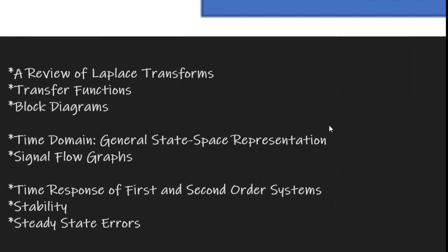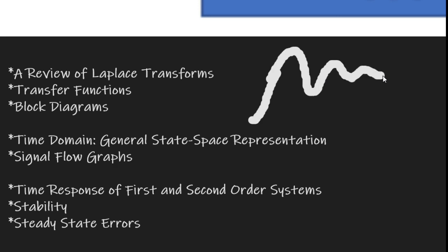And maybe, when it is going to the steady state, let's say it starts from here and the steady state is somewhere around this position. It's possible that along the line, it first goes beyond that steady state, then comes back down, goes up again, comes back down, goes up again, and now comes back and settles. Or it is possible, on the other hand, that it just goes straight like that to settle. It's possible it takes a short time, it's possible it takes a long time. All these will be part of the specifications that are important when you're starting your design.